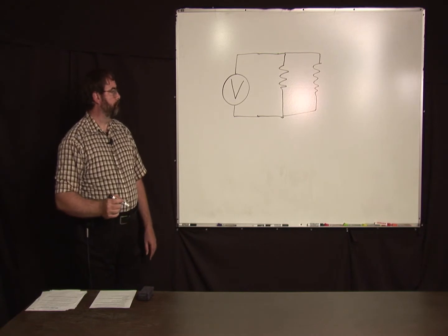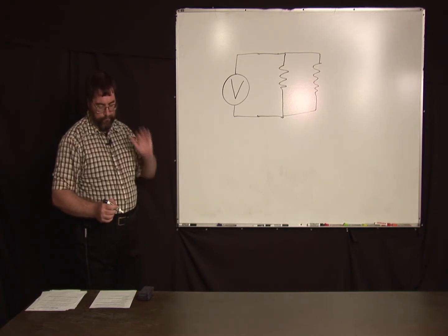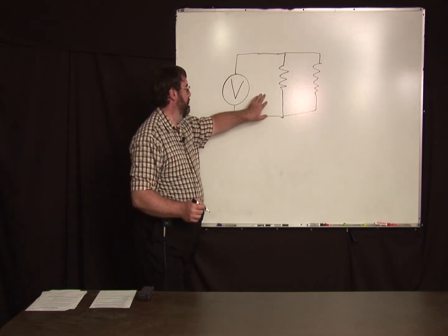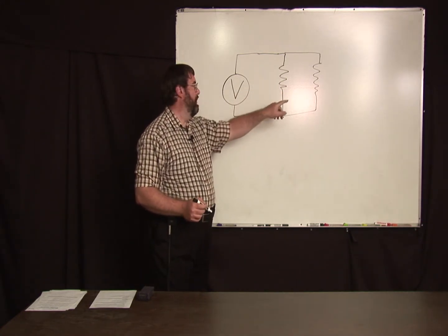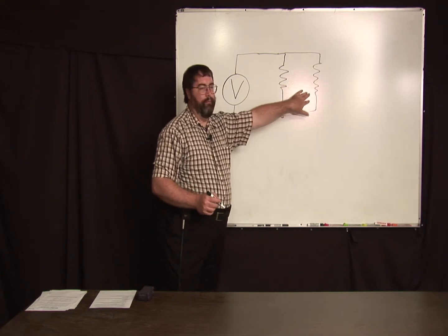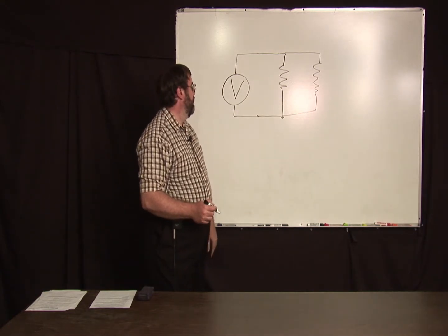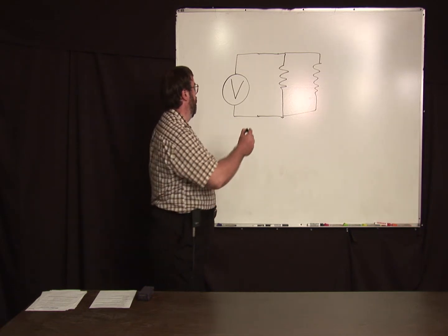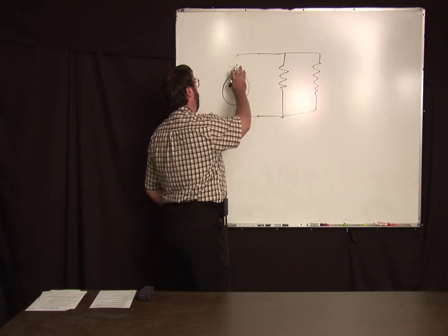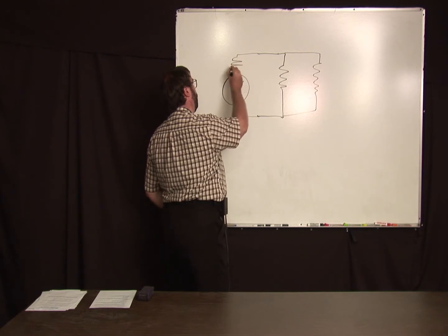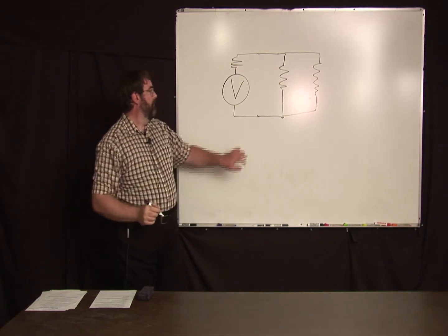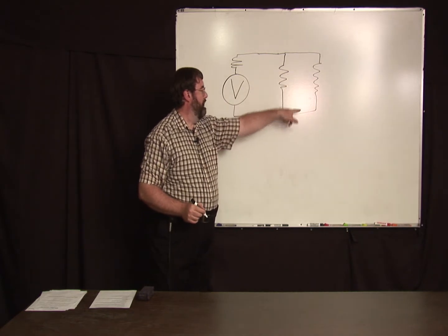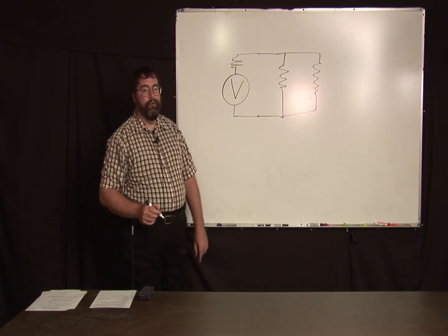So whatever voltage you measure, that's the situation you are in. There's probably some battery or something back here. But so you can measure the voltage. Now, the problem is all real meters have some internal resistance. So what this is essentially is something that will divide the voltage.